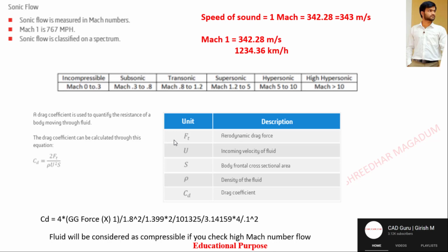Talking about coefficient of lift and coefficient of drag, so how are you going to calculate this one? If I consider SolidWorks Flow Simulation, you will get the lift and drag force. According to that, you can formulate the equations to get the coefficient of lift and drag.